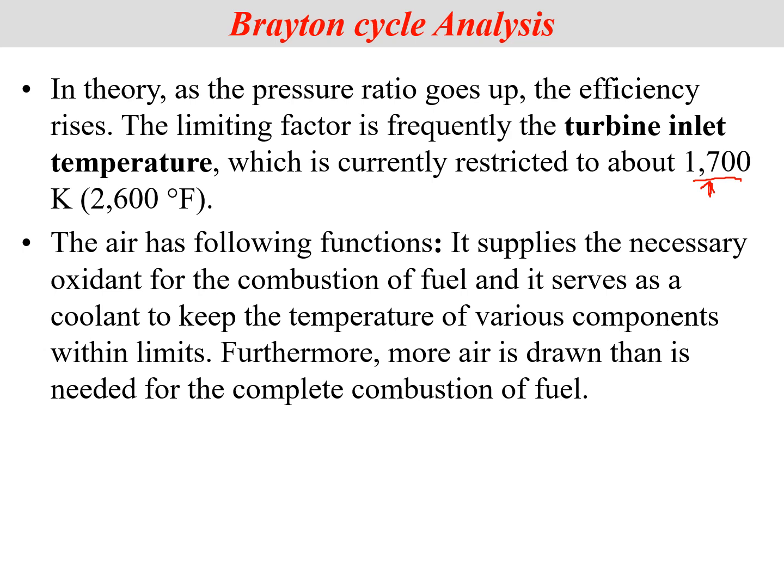A common question that can come up is that sometimes you see flame coming out of a jet engine, right? If you have ever seen videos of planes, you see a lot of flame coming out of it, and the flame is generally much higher than 1700 Kelvin. So what happens there is something called an afterburner. What does an afterburner do? When we are running a jet engine, we are taking in a lot more air than necessary for combustion of fuel. So what happens to that air? That is also available to combust at the end of this whole process.